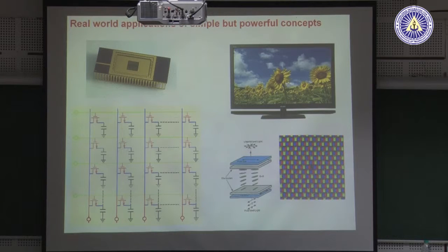So, showing to the students that, look, the DRAM that you put in your cell phones and your laptops, at the heart of DRAM is nothing but a capacitance, which acts as a memory element. And the RC circuit that you are studying helps us understand, for example, the refresh rate of a DRAM. So examples like this, once they are brought in, of course make things more interesting.